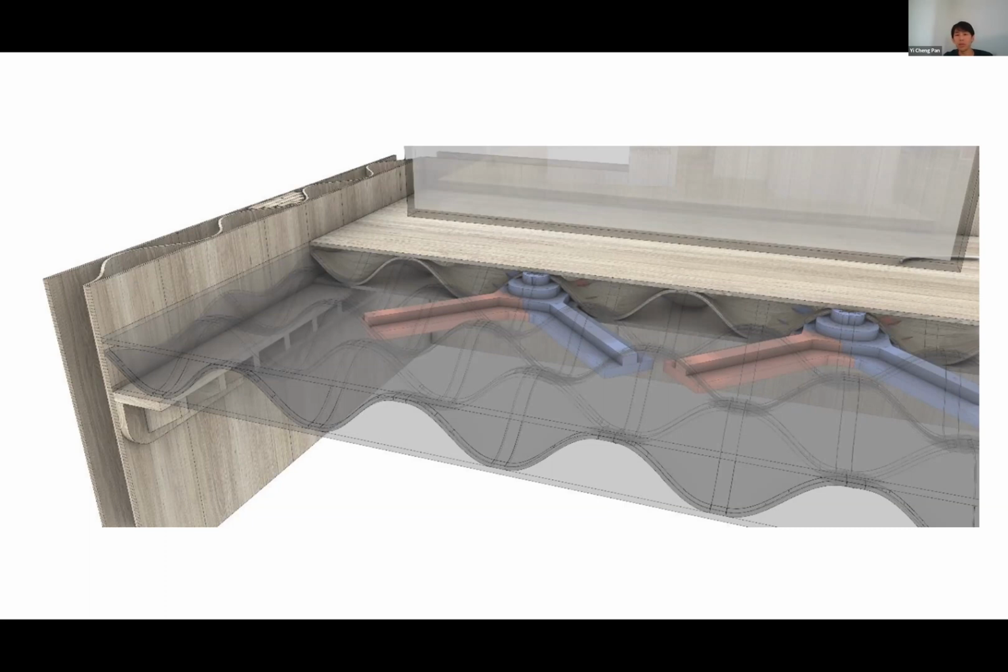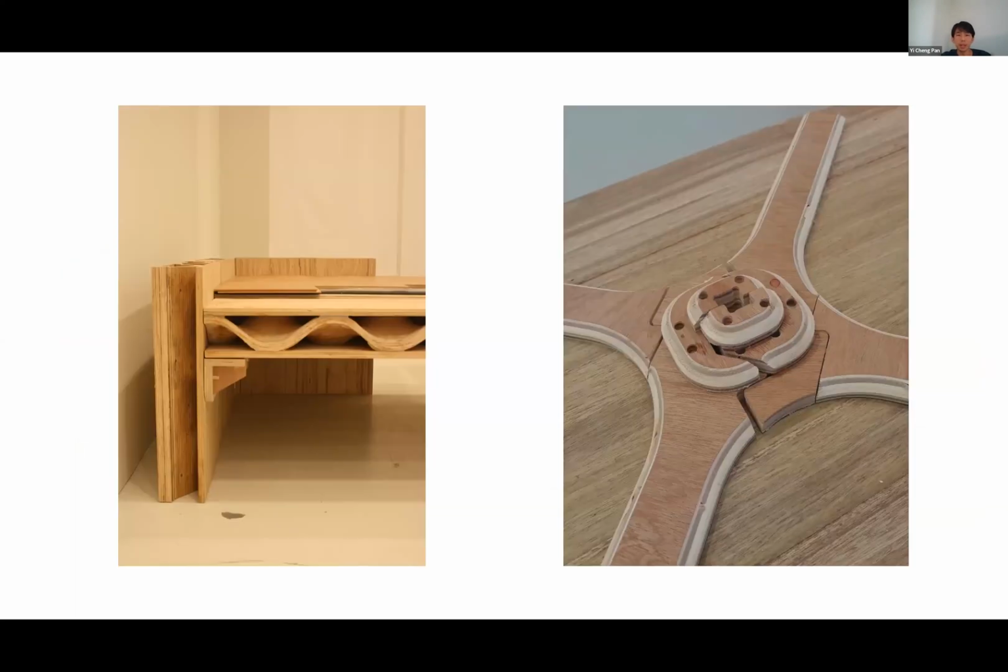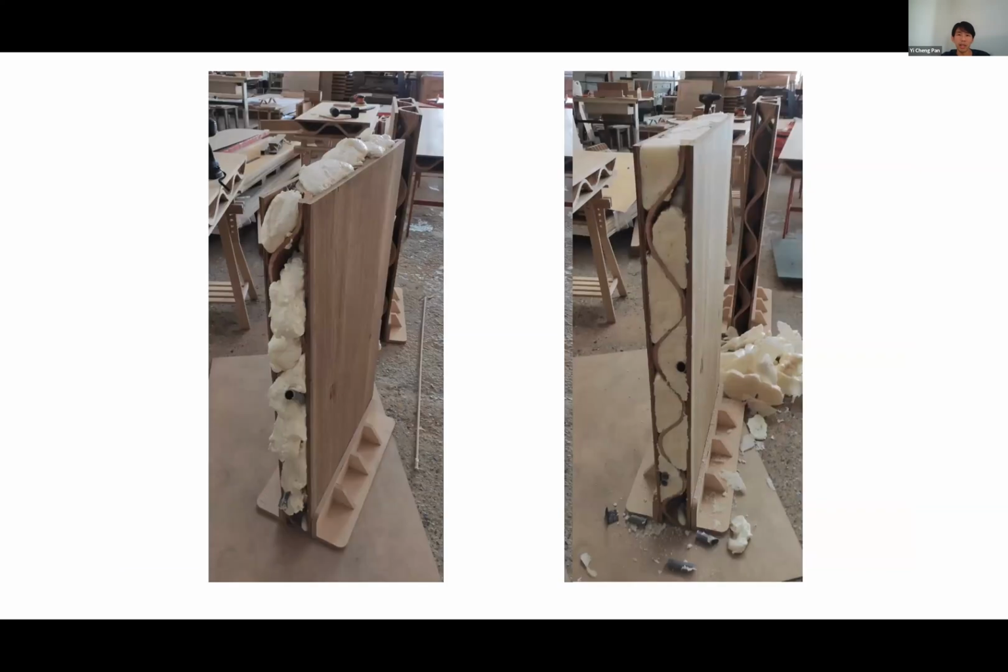So we also looked at how the panels are joined together. So here we were inspired by some Japanese joinery where you will knock in a piece to tighten two parts together, pull the two panels together. This is represented by the blue and red members that are hidden within the corrugation. So each panel comes in now 600 wide, and we can go up to 5 meters in length. But in the mock-up that we did at NDC, National Design Center, it was 2.4 meters in length.